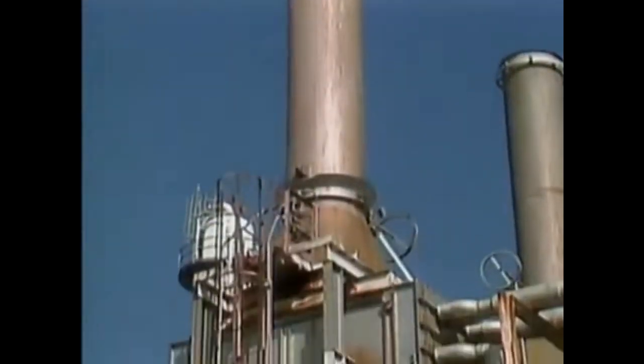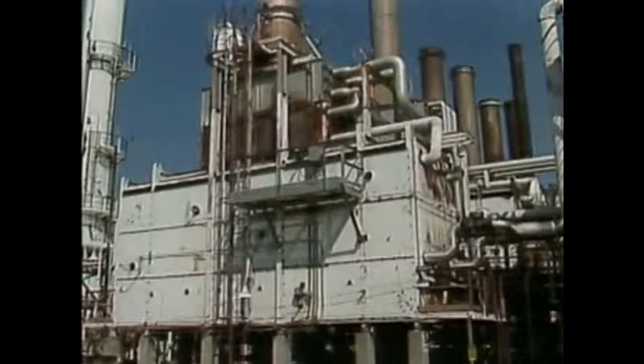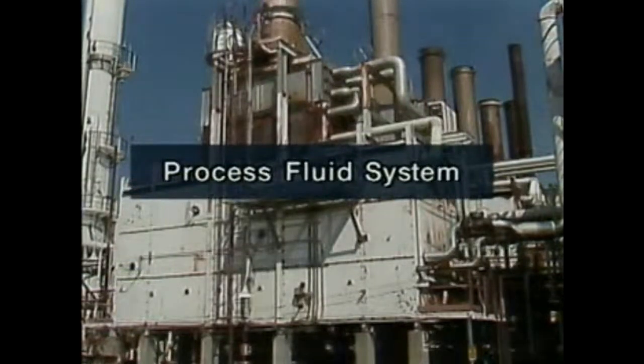If the flue gas temperature is too high, there could be a fire in the convection section, or the furnace may be operating above the normal firing rate. An excessive firebox temperature can overheat the tubes and refractory and damage tube supports. So far, we've seen furnace instrumentation related to fuel supply and air supply. Now we're going to look at the process.